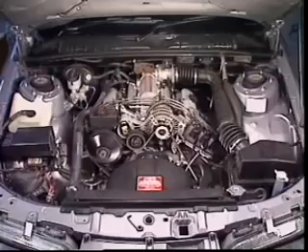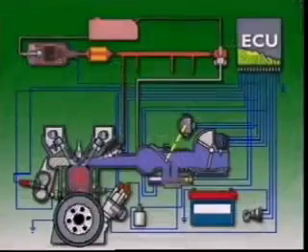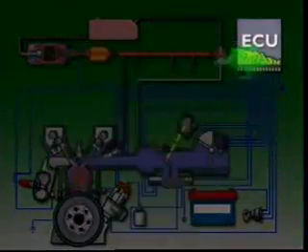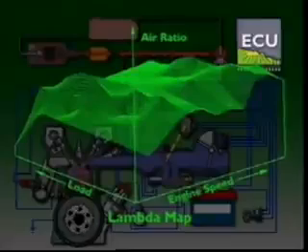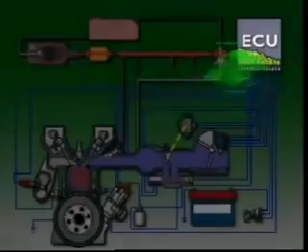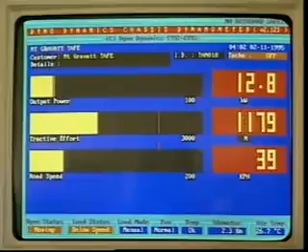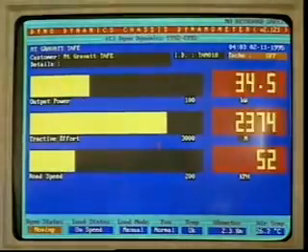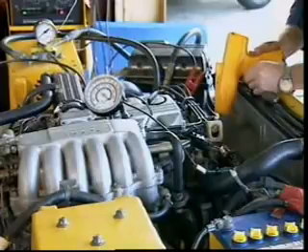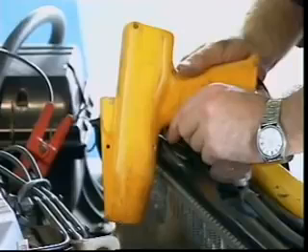The ECU adjusts quickly to changing conditions by using what are called programmed characteristic maps, stored in the memory unit. They are programmed into the ECU just as data is programmed into a computer. Characteristics means the engine's operating conditions, and they are called maps because they map all of the operating conditions for the engine. They're constructed first from dynamometer tests, then fine-tuned to optimize the operating conditions. This data is stored electronically.